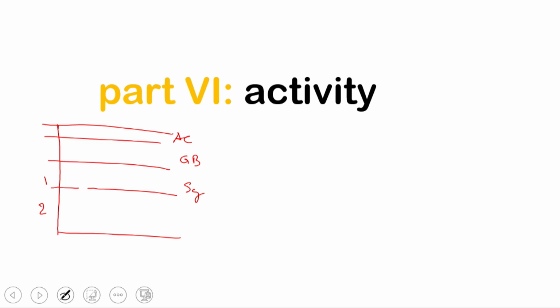So let's say you do have those. AC, obviously, there is no flow through here. But then you said, okay, for time equals the first month, month number 1, we calculate that environmental factor, okay? And that's going to be an environmental factor in here for unfrozen condition. And in here, we're going to have an environmental factor for unfrozen, and here too. Depending on the number of sublayers that you have, this is unfrozen. So you're going to be using unfrozen environmental factors for them. You do the same for month 2, 3, 4.